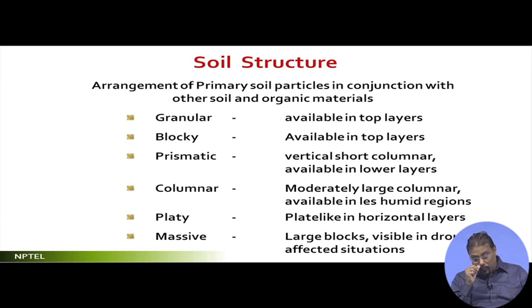It's mainly because of the geomorphological character of that particular soil: it is micaceous rock. Mica as a soil material or mineral is actually very strong. If it is a plate and you put pressure, it will take axial forces, no problem. The moment you bring it vertically up, you will find that it will slide. It is structurally very weak when vertically placed, but the mica itself is formed in nature horizontally. So you don't have to worry about it, but I do worry for one reason.